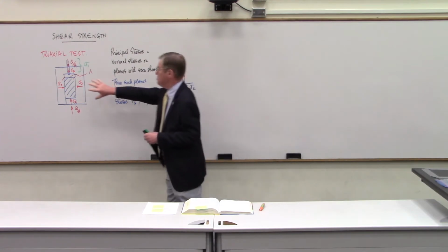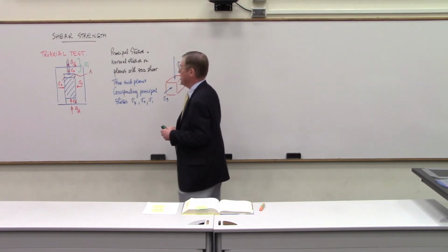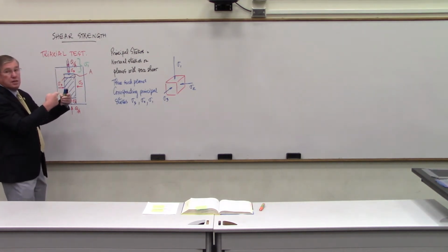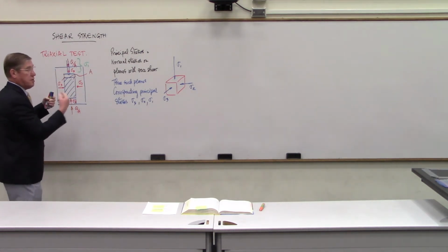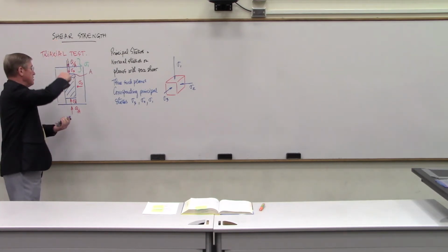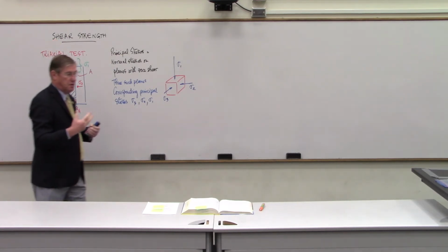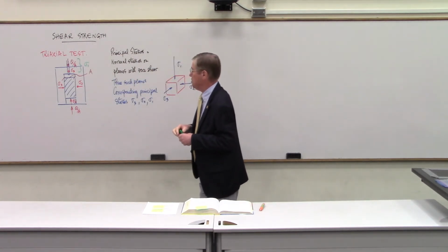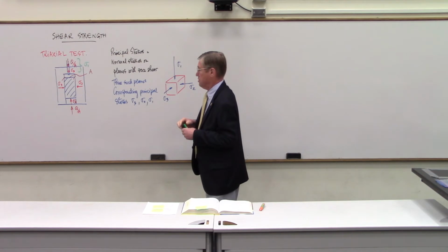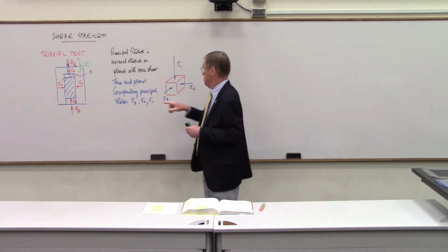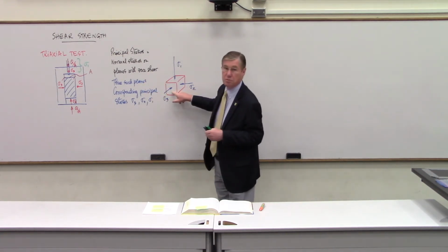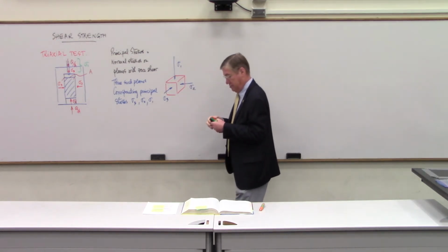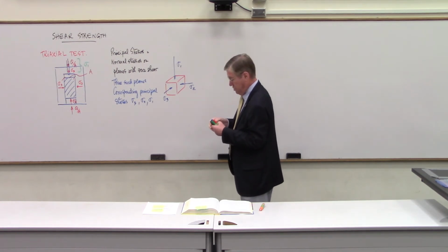So when we run this triaxial test, we apply sigma 3 in this direction, sigma 3 in this direction also because it's all the way around, and then we increase the stress in the vertical direction, and that becomes sigma 1 because it becomes the big one compared to sigma 3. So in the triaxial test, sigma 2 is equal to sigma 3. So it's a special case. Even though we call it triaxial test, sigma 2 and sigma 3 are equal to each other.